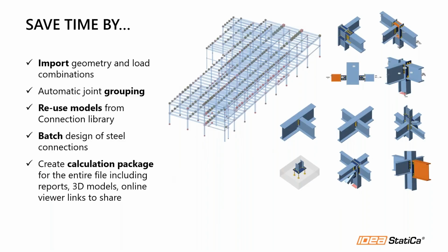Finally, you will save time by creating high quality deliverables from a single source, okay? So it's quick and easy to create these reports for multiple connections. You can see here that we designed multiple shear tabs. This was the typology that was the most repeated, and also this one. But we are also looking at joints that have multiple members, moment connections, bracing connections, and even base plates.